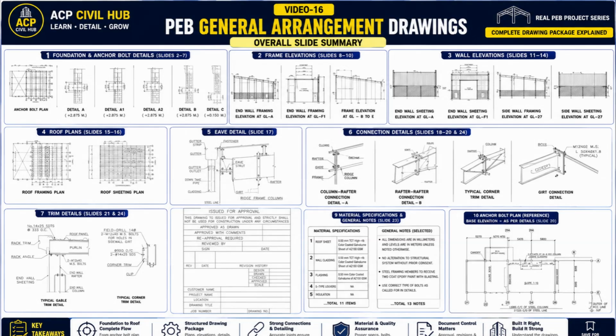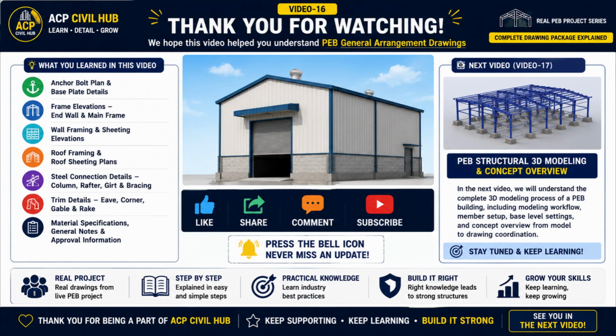The key takeaway is that a complete PEB drawing package connects every stage of the project, from anchor bolt setting and structural framing to roofing, cladding, connections, and final project documentation. Understanding how all these drawings work together is essential for accurate detailing, fabrication, erection, and successful execution of a PEB project. Thank you for watching this complete PEB General Arrangement Drawing explanation.